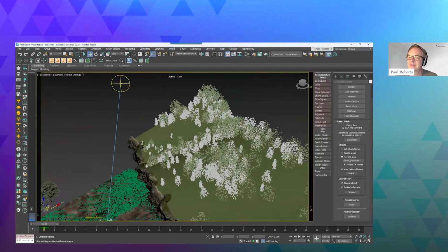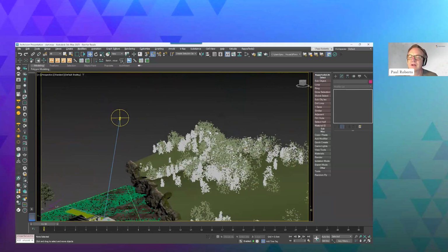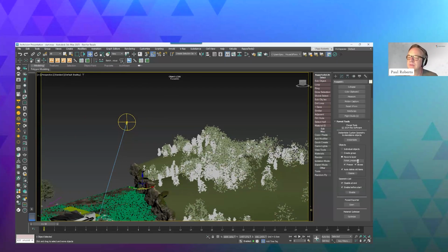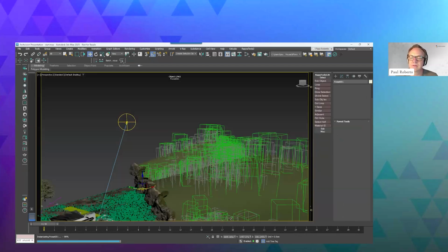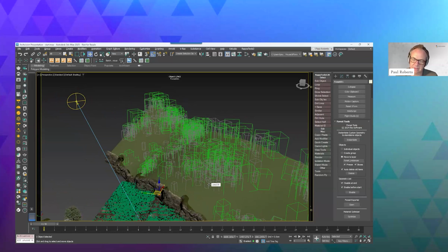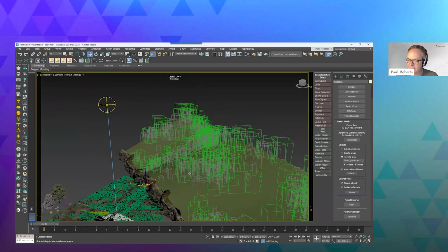And what that means is, I make sure I've got the actual trees here, and you basically hit this button here. It converts it to native instances, so no ForestPack plugin required, and then it will render anywhere.